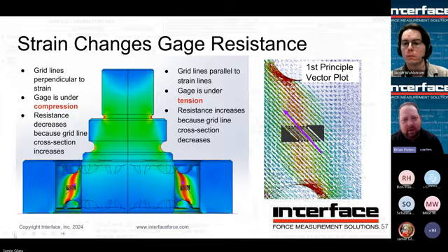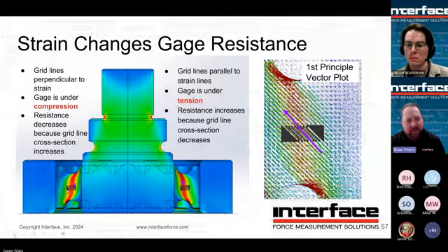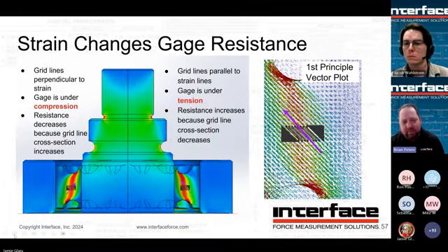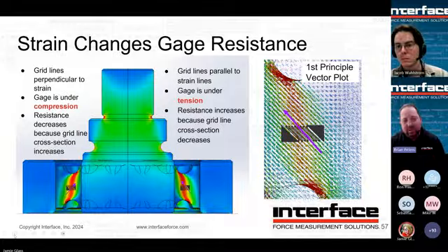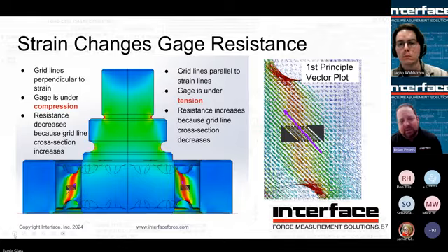The second thing I want to highlight here is if you go through some of our products, you're going to see that, as you saw earlier, our standard 1200 series has the female threaded hole in the top, right? Well, if you look at this, you can see how the force applied at the end of that top section, which would be threaded, transfers all the way through the center portion out to the outer beams where the gauges are. So our 1200, our 1100, or 1000 series will have a female threaded hole. We talked about the importance of mechanical mounting and the thread engagement and making sure you've got good tight connections and potentially even preloading. That is because it lends itself for much better consistency of how that load propagates through